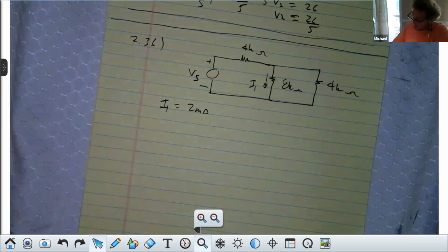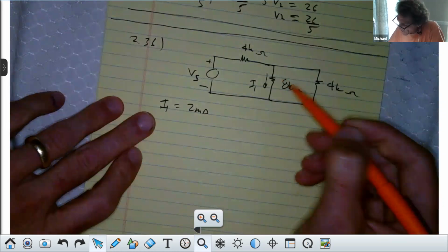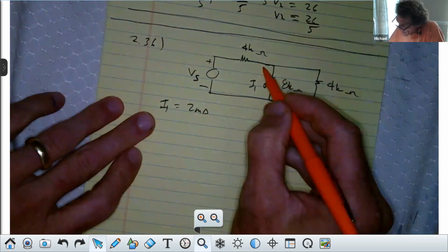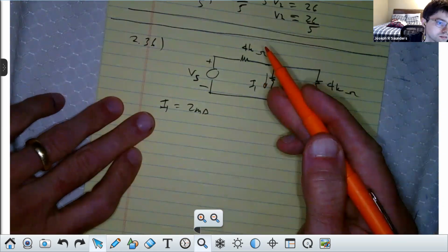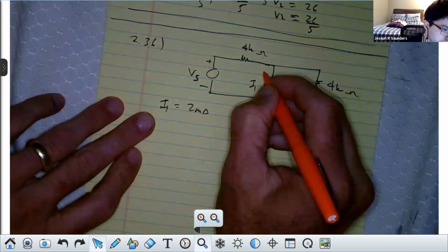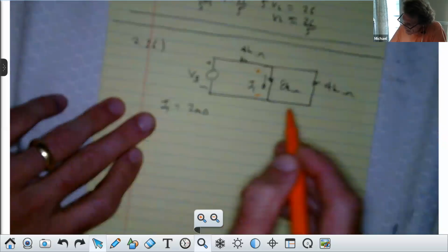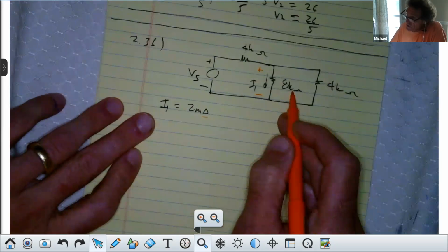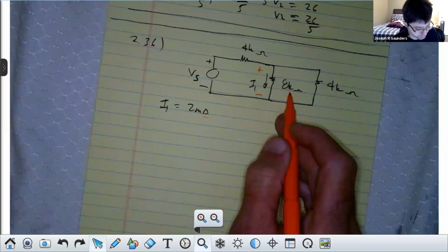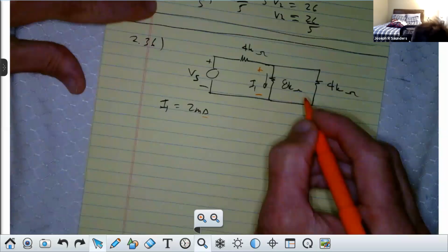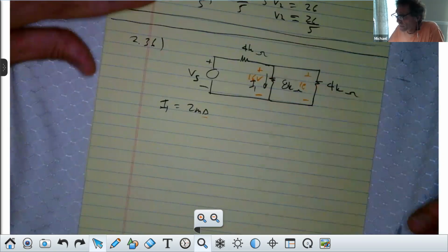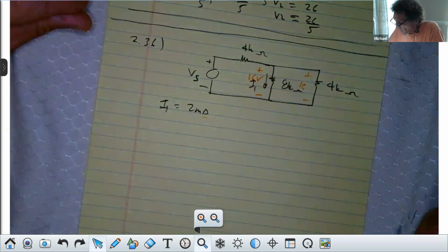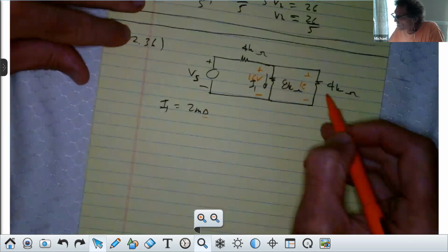We've got a resistor, and we know the current through it. Do we know the voltage across it? Yes. What is it? It's 2 milliamps times 8K or 16 volts. Do you all agree? Right? Yes. 16 volts, right? Now, isn't that 16 volts also across the 4K? Because they are in parallel, right? Y'all see that, class? Yes, sir.